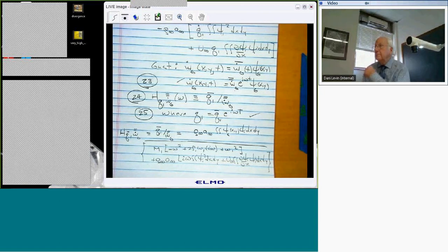Okay? So I've computed the transfer function. Now, when I square this, I'm really multiplying the transfer function by its complex conjugate, which is going to make that square a real number, even though I have imaginary numbers in the transfer function itself, which is good, because eventually I'm going to compute the mean square, which is a real number.